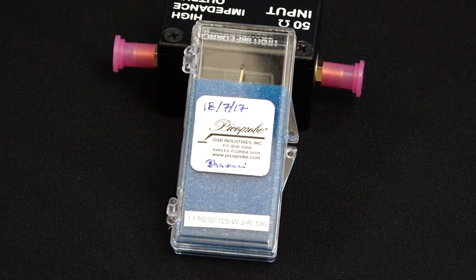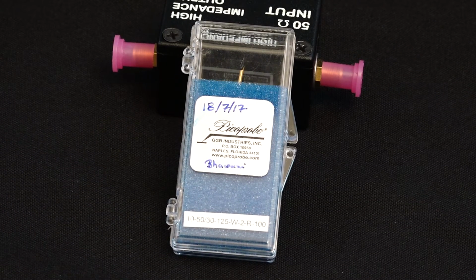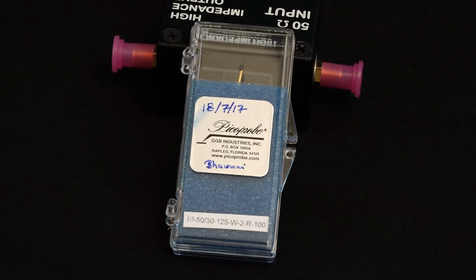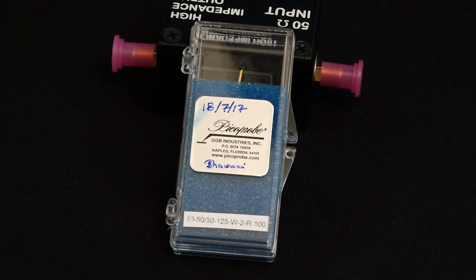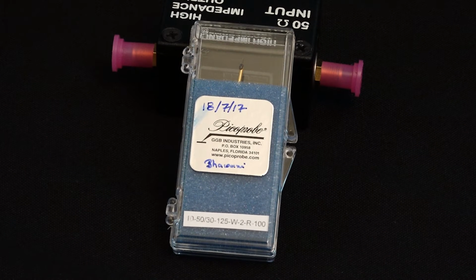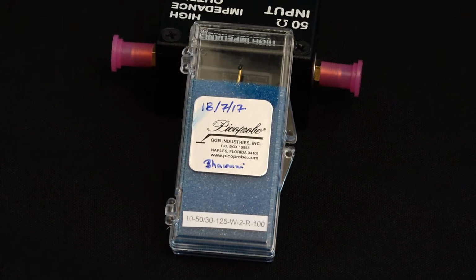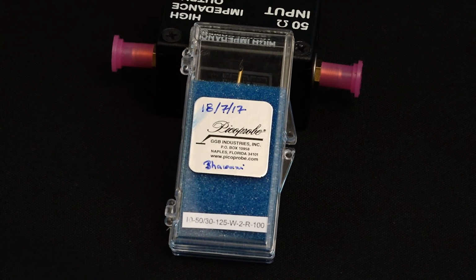That is something very important you have to take care of. Many times in the starting days we made mistakes as to which pin was signal and which pin was ground, and you see very spurious results in that case. Both the grounds and both the signals have to go on a single contact pad. So both the signals will go to one contact pad and both the grounds have to go to one contact pad.